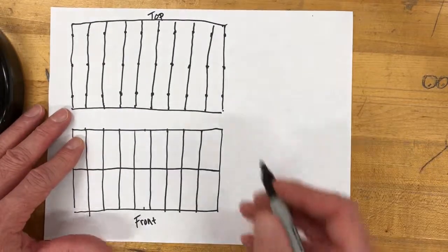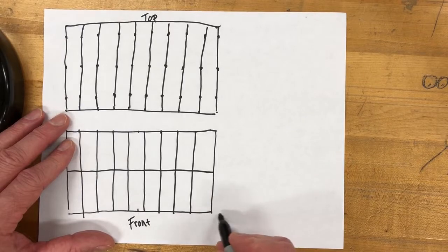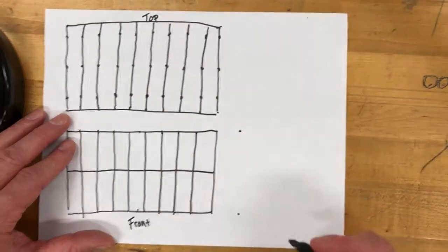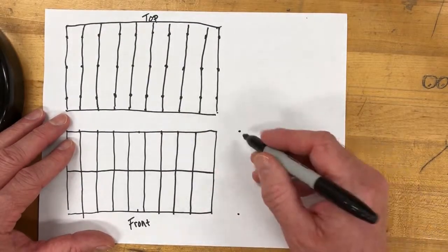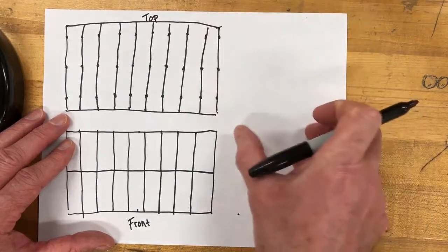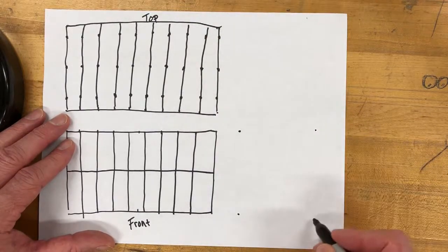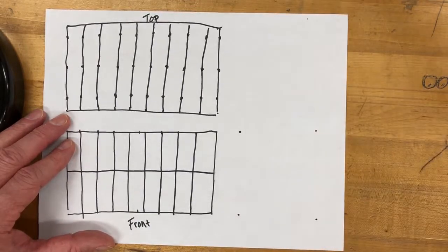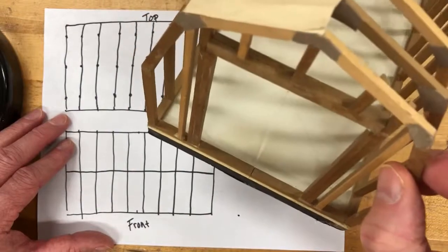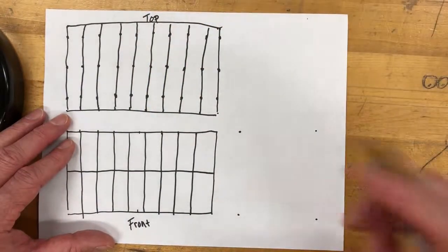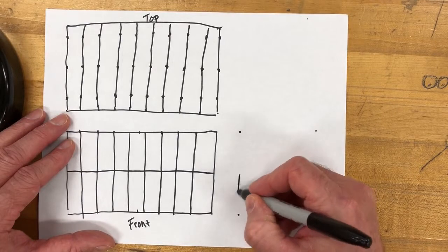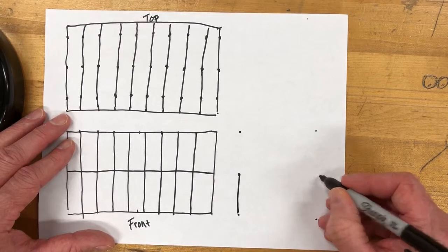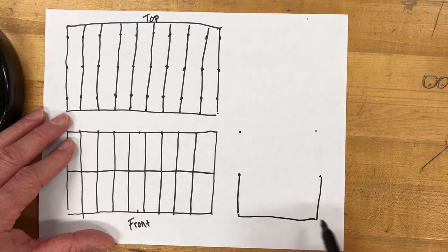Now the right side view, once again, what I'm going to do is just project over. I know I want to leave a little bit of room between my views. I know the height of it here because I've already identified it in the front view. I know it's the same distance here, so it's 8 feet this way. So I'm going to have roughly a square here. Now I'm not going to draw in the square because, when I take a look at the model, it's not square. It's got a gambrel on it. But I am going to put the sidewalls in like this, and I know where their location is because I can project them over from the front view. And then I'm going to connect up the bottom just like that.